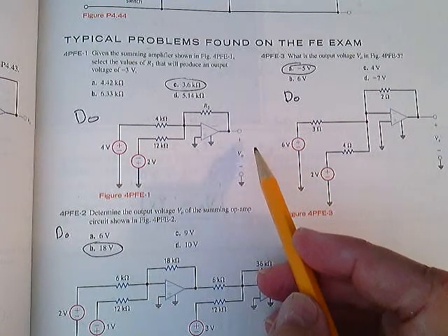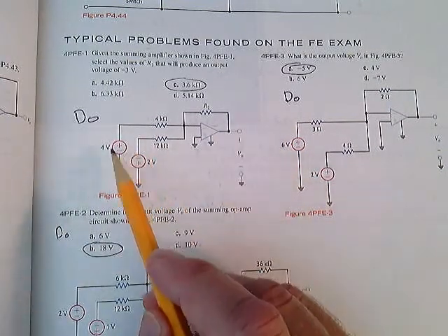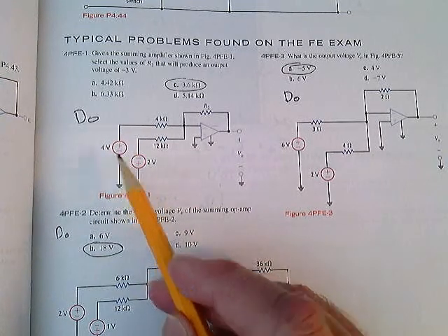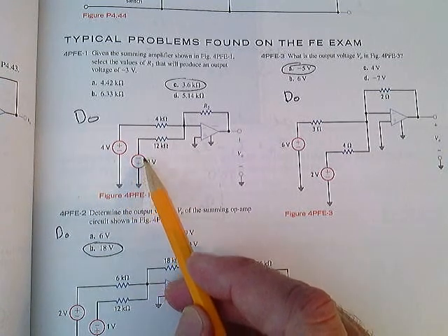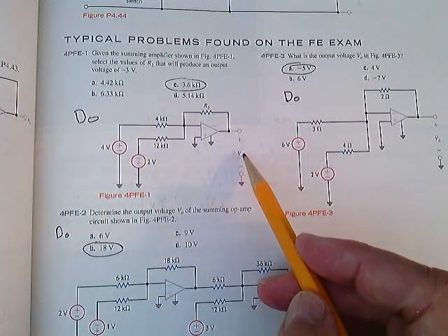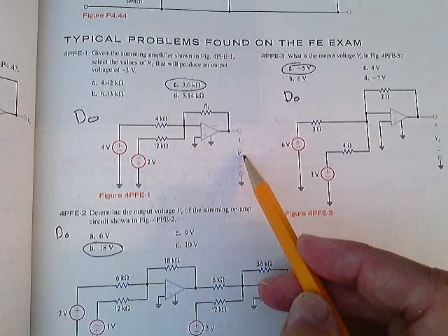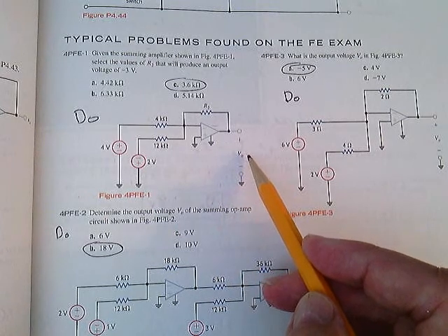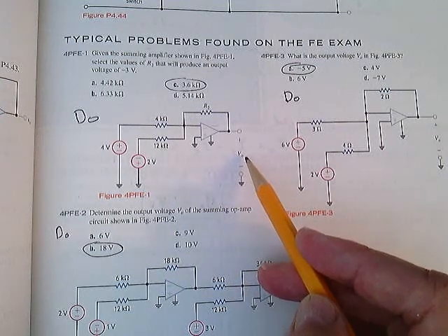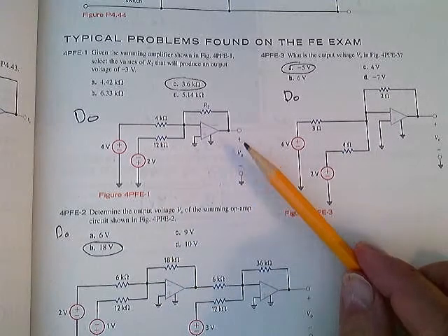And you note that. And then you go back here and you short this one, and you see the result of this minus 2 volts. And you get the gain output, you get the voltage output for it. We're going to call that V out double prime. And then you algebraically add up your V prime and V out prime and V out double prime, and you should be able to analyze this circuit right here.